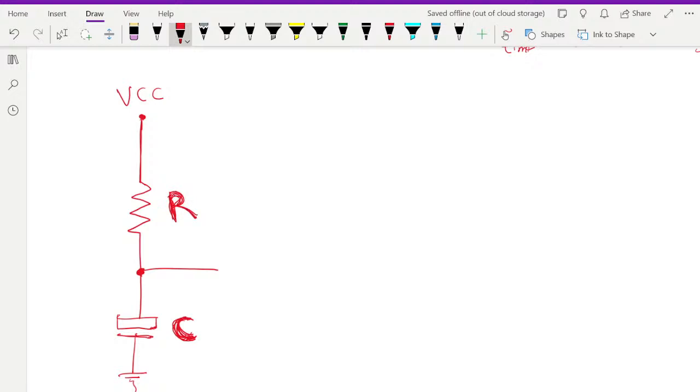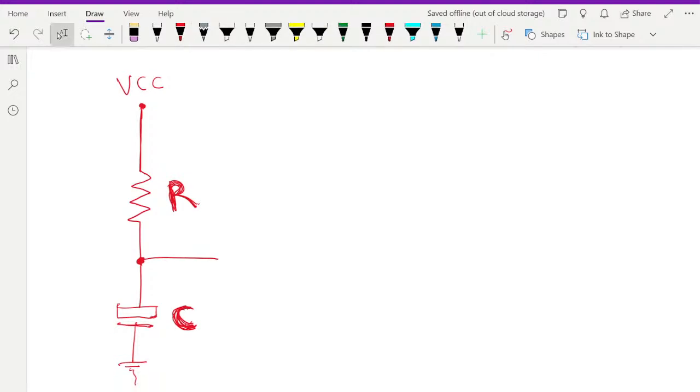As you've seen, if you just pick any value of resistor and capacitor, you might have some problem. So they had done some simulations and come up with the values of RCs to be used in the system, but someone decided to use a different value, 10 times the value, and it wasn't resetting as it should. Sometimes it does work, but sometimes it doesn't. So I recommended they go and change that, and everything worked fine. It was actually leading to a recall at the time, but something as simple as a resistor and capacitor can cause that kind of problem.